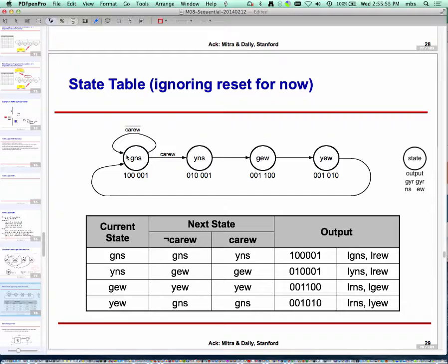And then you could feed it, it will lead to a very hairy design. So what you would normally do, if you want to stay put in a state for a longer time, is use your fast clock and then use some sort of a timer. So you'll say, count 5 seconds for me, and then send me an input. Yeah, but for the state, I want the reset to be faster than the transition.